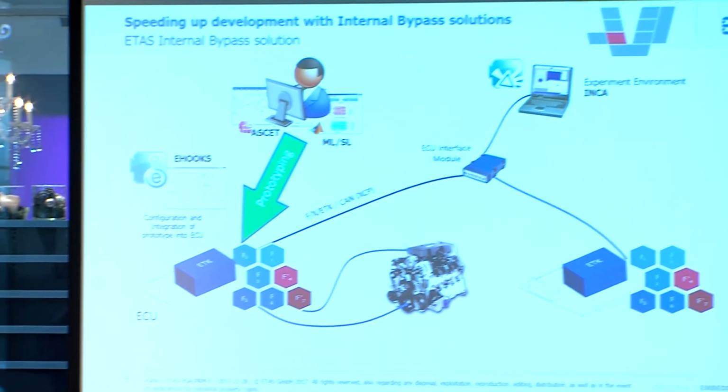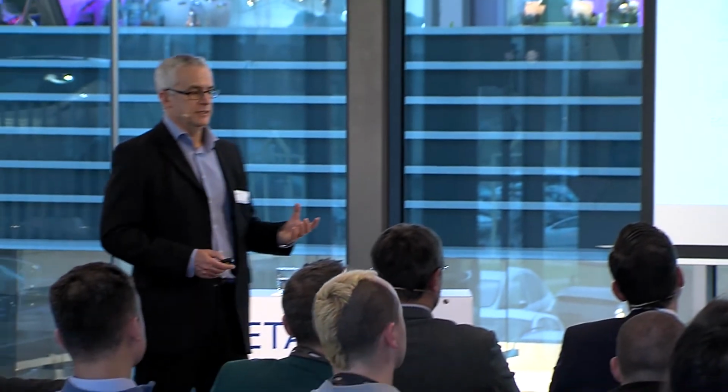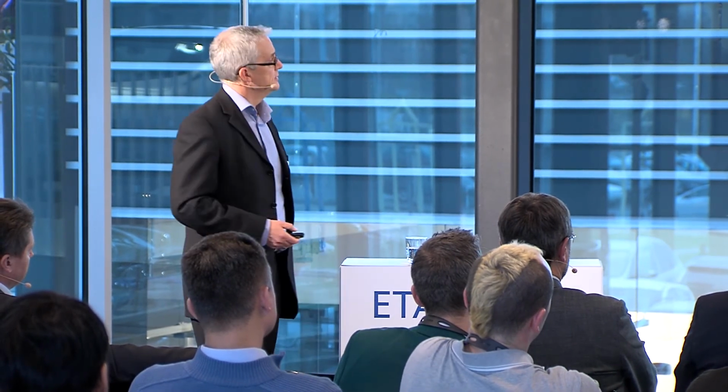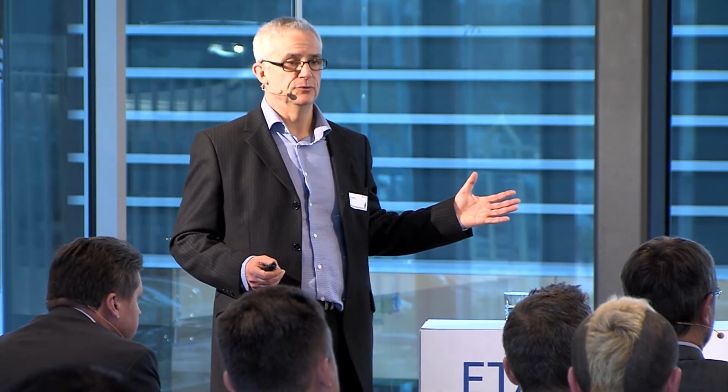So when you combine this intrinsic benefit of internal bypass with the use of an FETK connection to the ECU, for example, it allows data acquisition from functions running with cycle times down to about 10 microseconds. So 10 microseconds, it's very fast. This makes it the perfect solution for validation of functions running even in the fastest cycle times we're seeing in today's market.